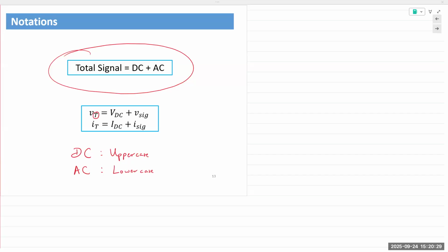Okay. All right, so just using the example of the transistor, there are three terminals of a transistor: collector, base, emitter. One of the most common voltages we measure is VBE, which is the voltage at the base and the emitter. So if I was to write the voltage, lowercase v, uppercase B and E. VBE is voltage measured at the base with my reference at the emitter.